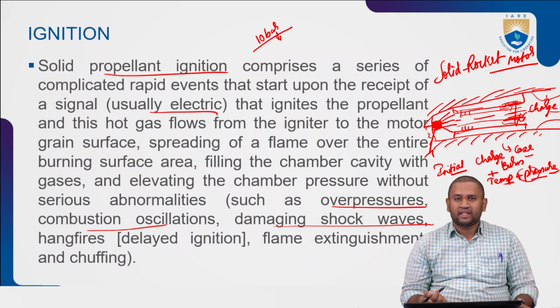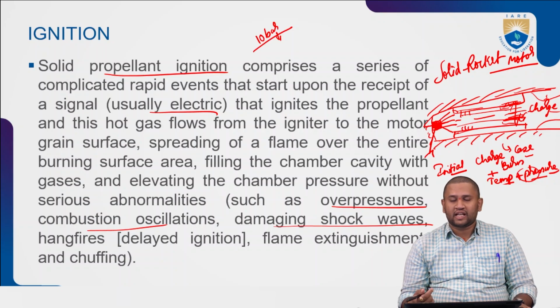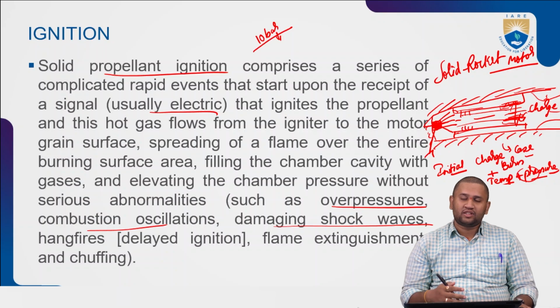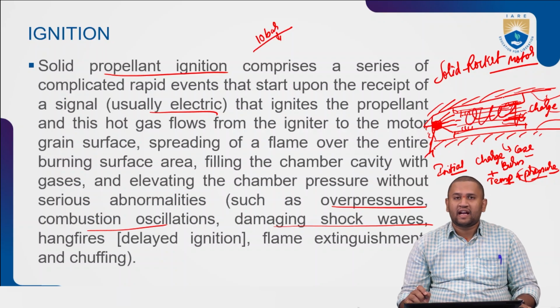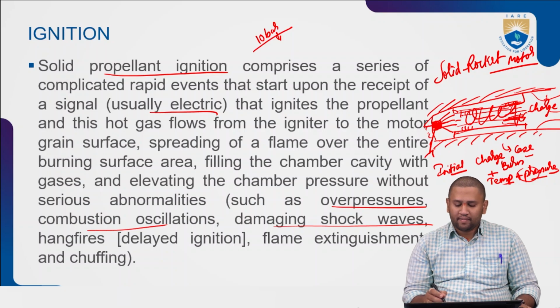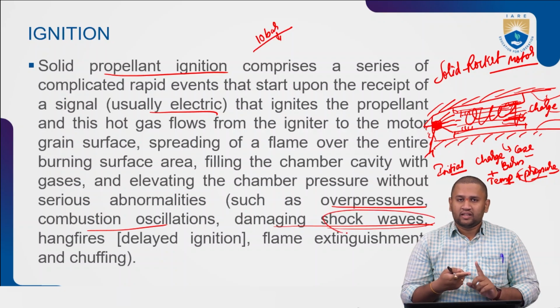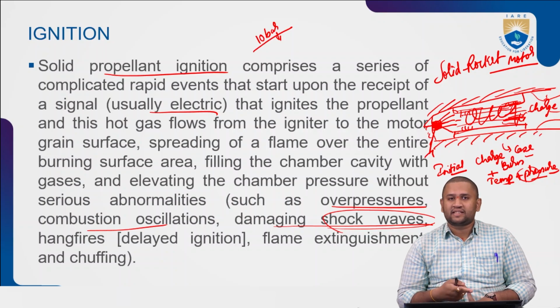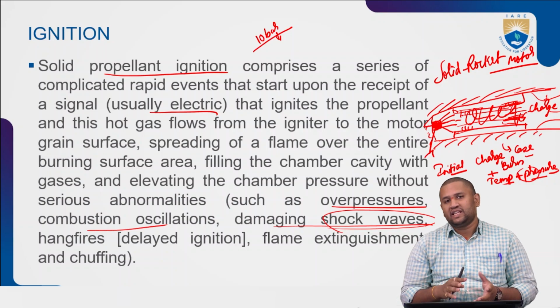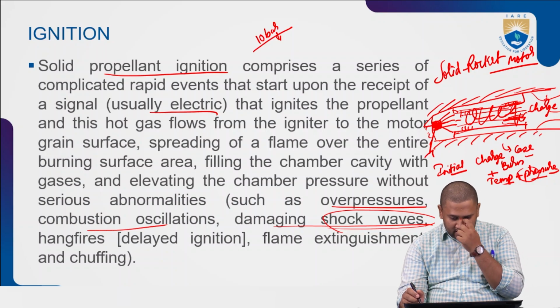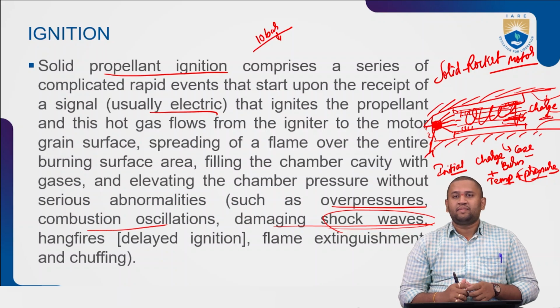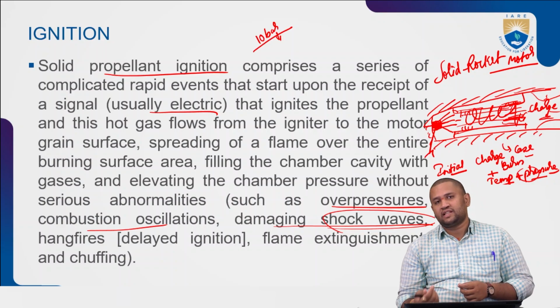The waves, particularly the exhaust pressure, as it gets out, the shock waves that are being produced inside the cavity due to the burning, what happens? These shock waves might be damaging in nature. It might damage the charge or it might damage the case in which it is being fit. Now these shock waves tend to move further towards the nozzle, giving me the damage to the nozzle itself.